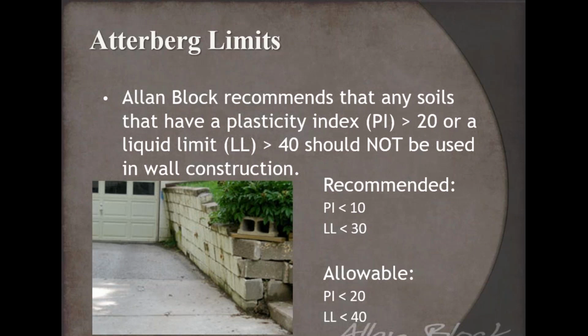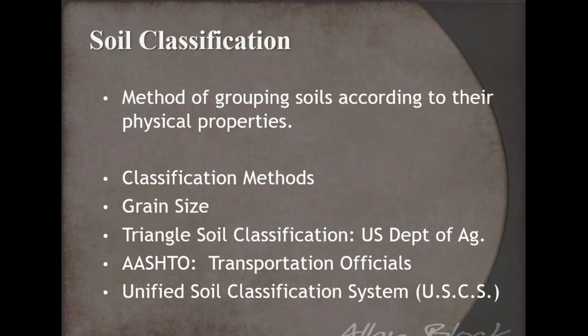You can say, yeah, you don't have a sand and you can assume a clay, but we've all been part of projects where clay material might be heavily expansive or clay material might have a friction or a strength that is next to nothing. So that's where these tests really come into play. And that's where the classification comes in.